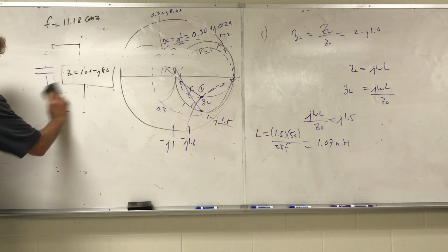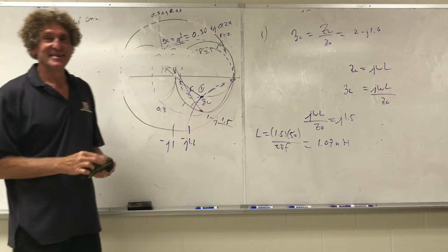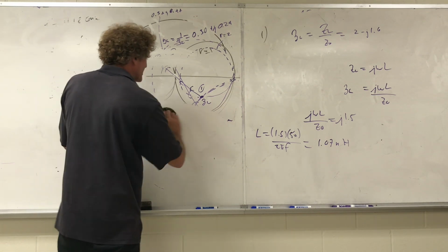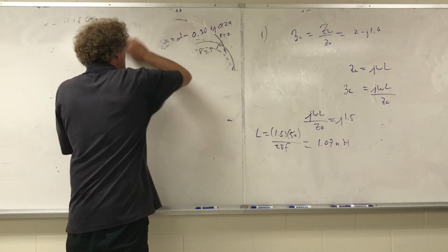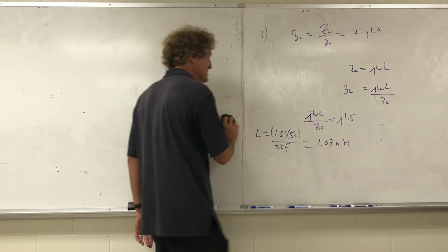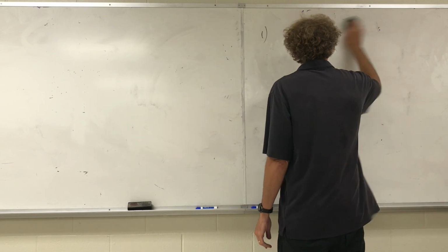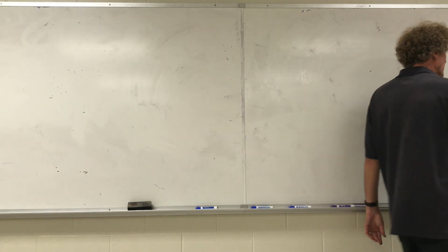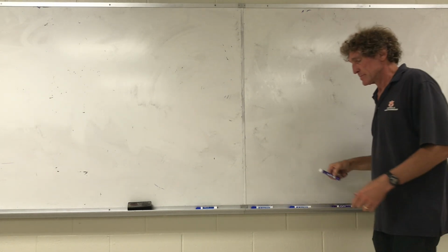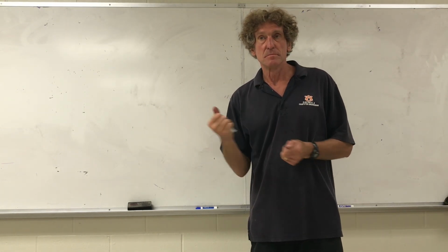He does it 4 ways, I think. All 4 are possible. It's not hard to do, but this means it's outside either one of those circles, right? It's outside the rotated one circle. Now that's the one you want, because it's got so many different ways to do it. I haven't been able to figure out, if you're outside both the circles and you're in the negative J region, at the bottom, is it possible to even have the shunt C element and then the series L?